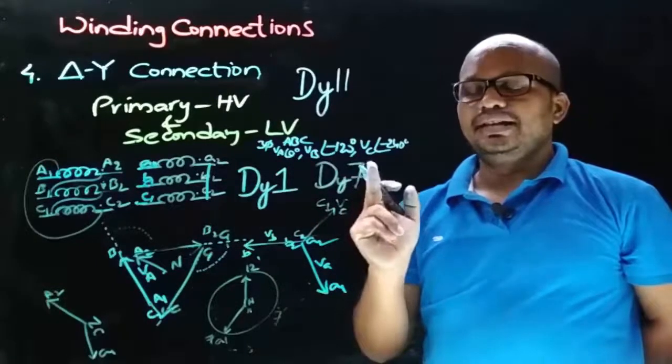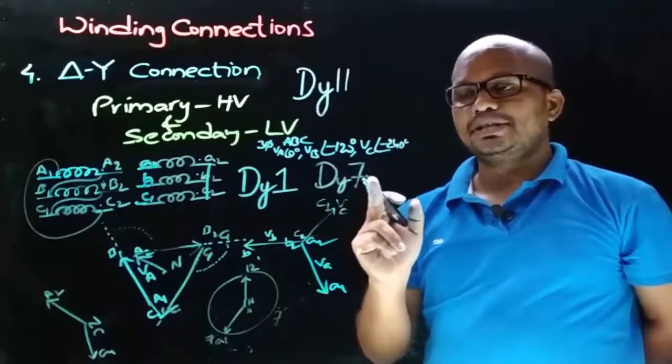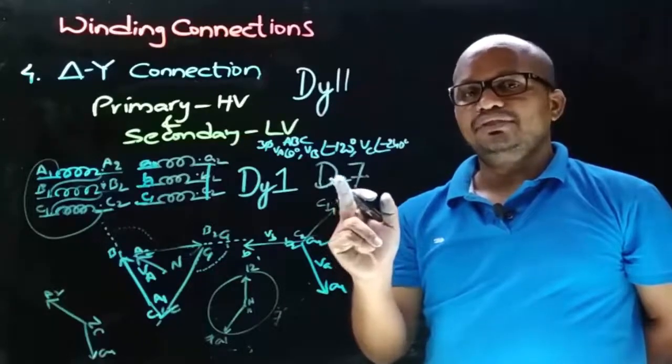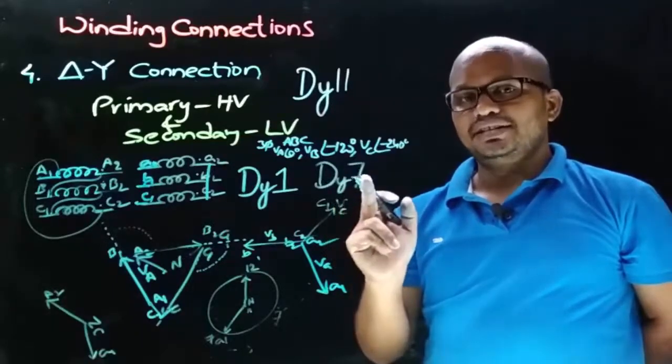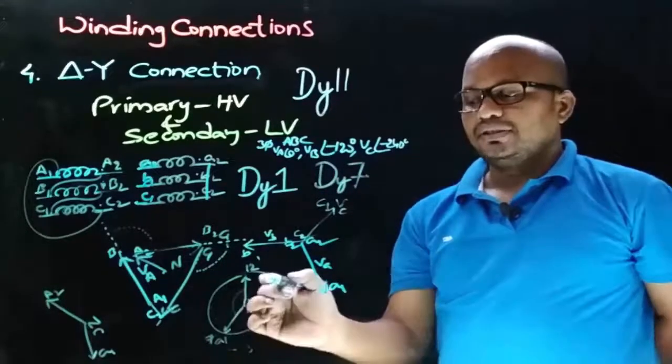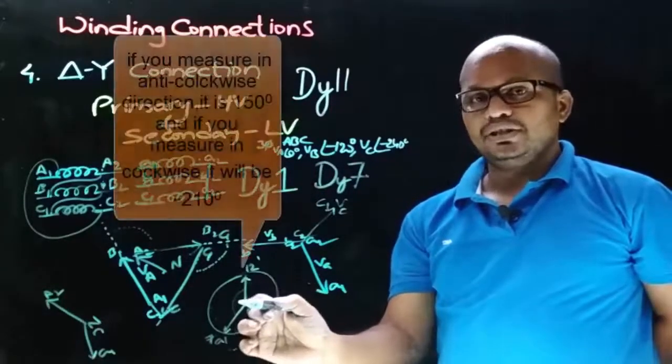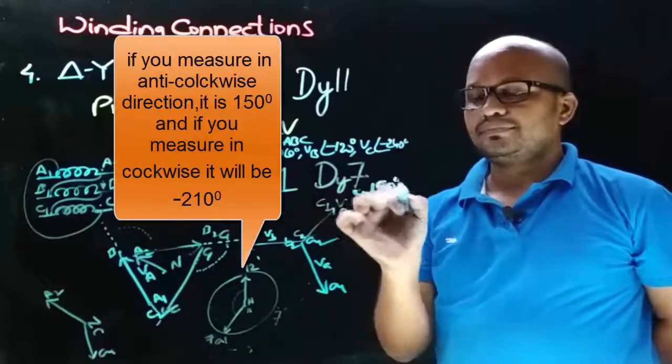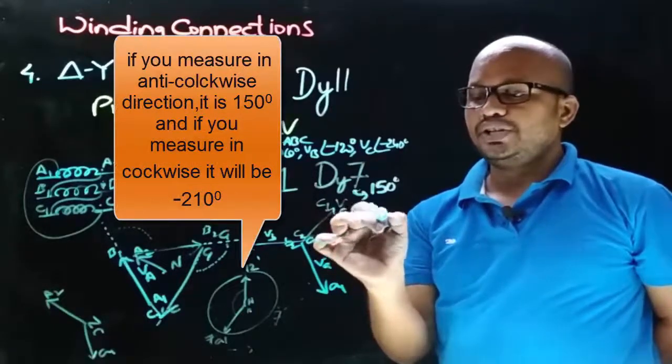It indicates the LV winding phase node voltage displacement with respect to the HV winding phase node voltage, given by the angle between the minutes needle and hours needle. The angle between them is 150 degrees, which can be written as 180 degrees minus 30 degrees.